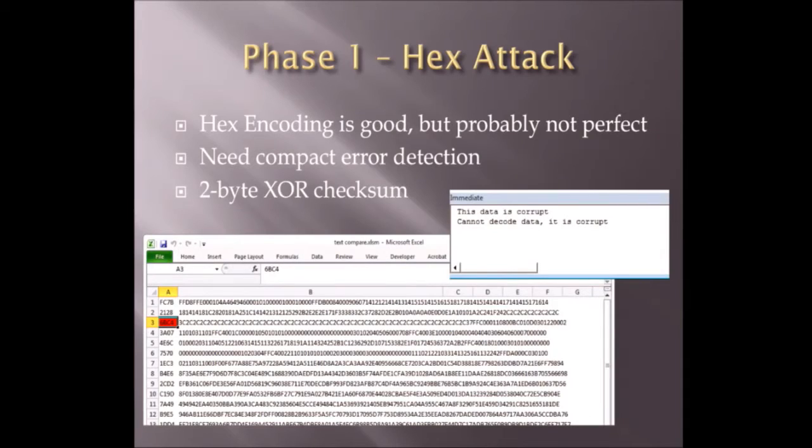But you'd think it'd be a pain in the butt to find these broken lines in your printout, but it really isn't. You would just take this exclusive OR, and you would find it in your Adobe document and find that line. And after you do this a few times, you realize there's a pattern to the failures. There's certain symbols that show up, like tildes and stuff like that, and any dots that happen to be between the lines of your actual printout will cause errors. And so you learn to find them very fast. It doesn't take very long to fix even a large amount of hex data using this method.